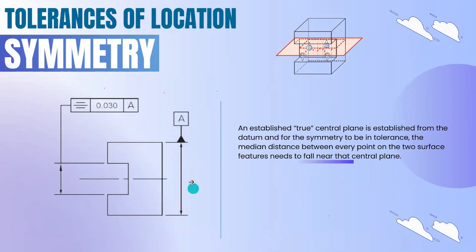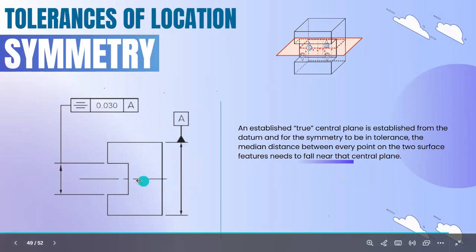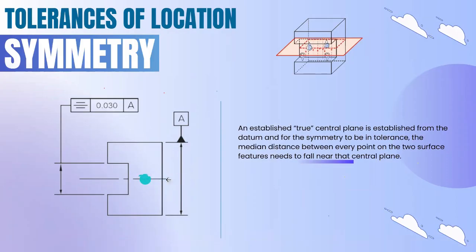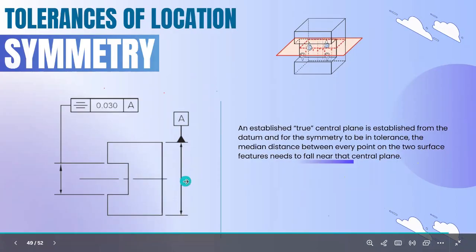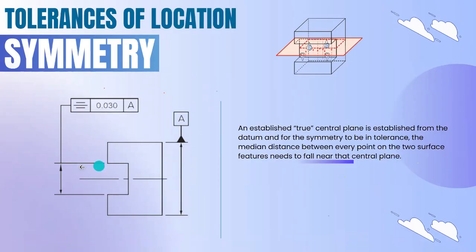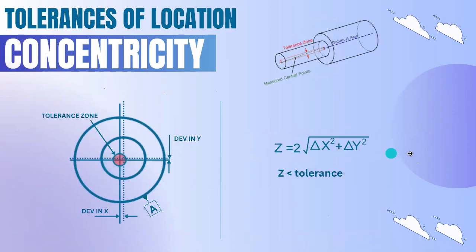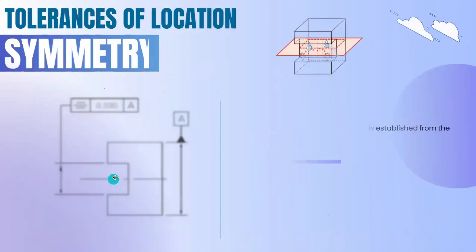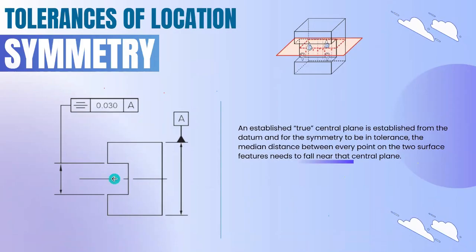So in this condition, we're going to take reference both center planes as the axis. The datum axis will be the center, and this plane will be the datum axis. Here, same as for the feature, they have extended it, given a dimension, and asked for symmetry for this feature. So the reference will be the center, and this feature axis will be the center axis. For this center axis, we're going to check symmetry. It should be the same in this axis.